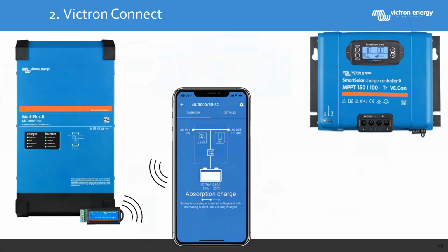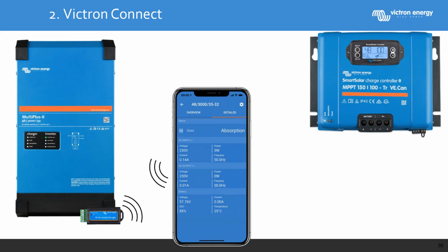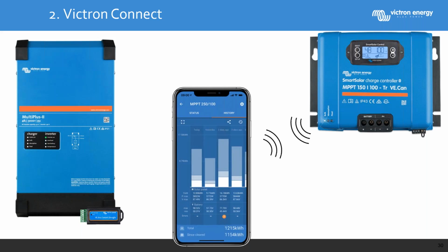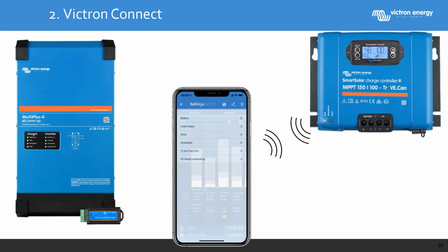So here you have an illustration of the communication using Bluetooth. If you want to connect to an inverter charger, what we call a V-Bus product, you need the V-Bus smart dongle that will generate the Bluetooth. Or if you connect to an MPPT, if the MPPT is smart, you already have Bluetooth. And if it's not smart, you can use a Bluetooth dongle. So with your phone, you can configure the complete system. It's really simple to use.